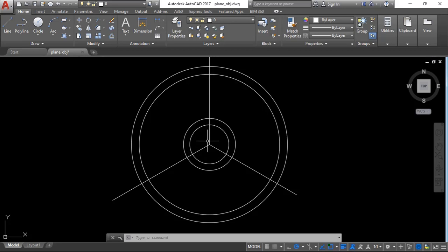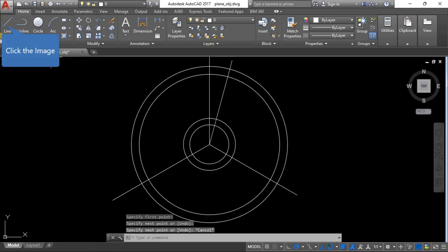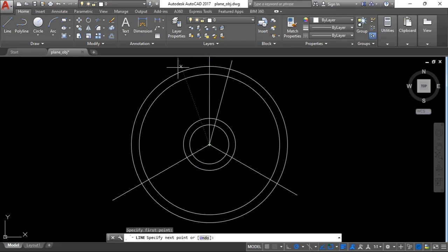Now we'll measure 30 degrees, 15 from this vertical. Again, getting the line tool, we simply subtract 15 from 90. That should give us 75. So look for where the angle says 75, right there. And we do the same thing here. On 90 degrees we add 15.